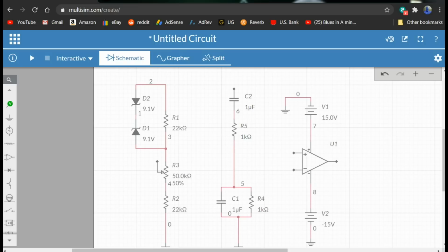At a particular frequency, like we said, 1 over 2 pi RC, the inverting input voltage and the non-inverting input voltage will be equal and in phase. So the positive feedback is just going to cancel out any negative feedback and the circuit will oscillate. But at any other frequency, our first voltage is going to be too small to cancel out the second voltage and it won't oscillate.